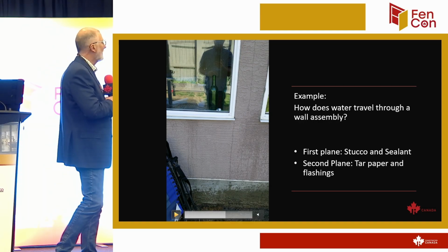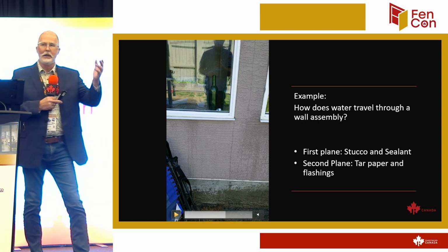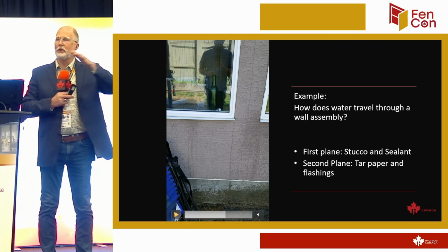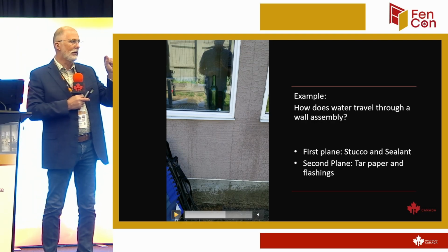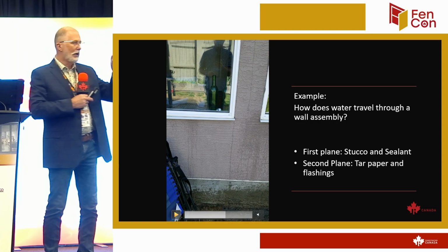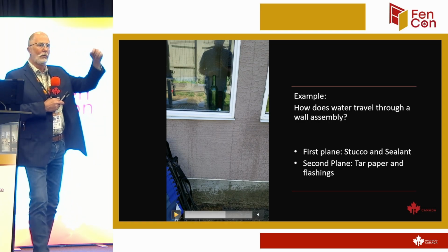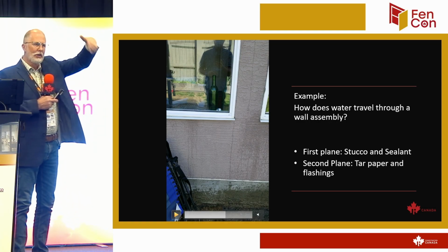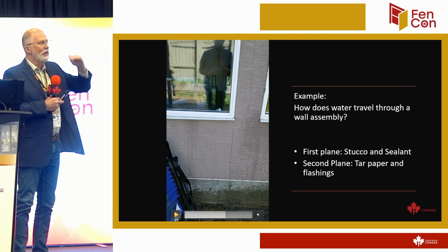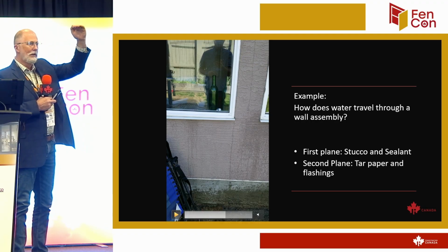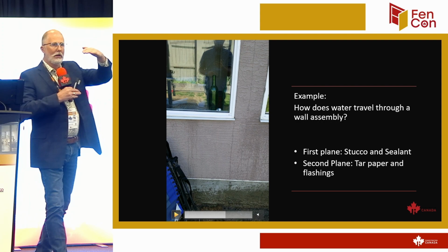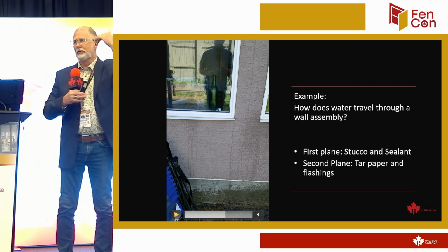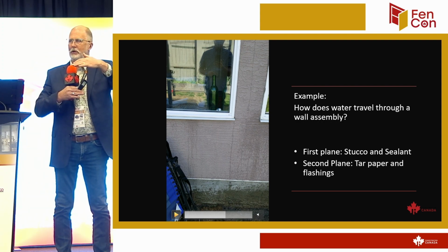So in this particular application, this particular house, they had installed everything correctly. They'd put a sill pan in there. They were still getting a water leak. But the water leak was coming from the fact that the water at that window head couldn't escape and come back out. So now it builds up a hydraulic pressure. And what's your overlap on your house wrap? Or you wouldn't use house wrap here. On your tar paper, it's about 4 inches.